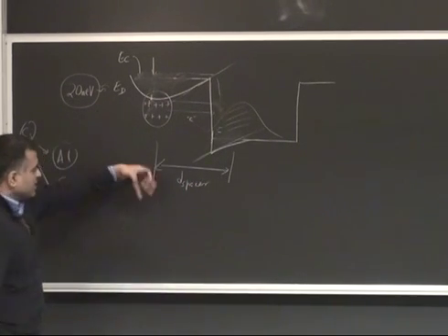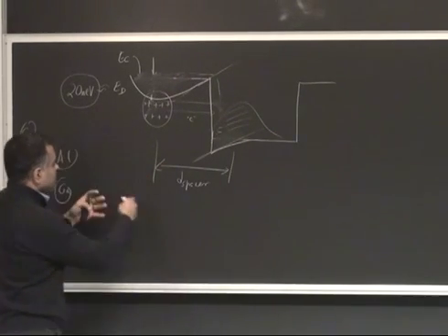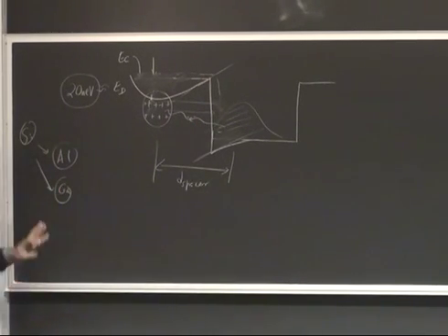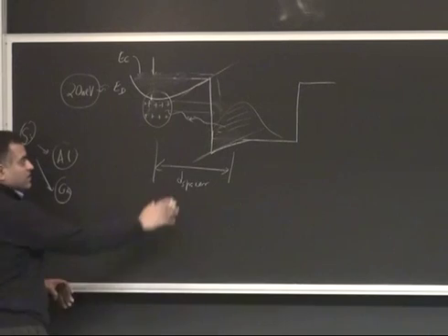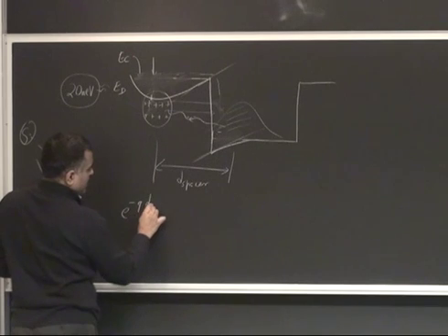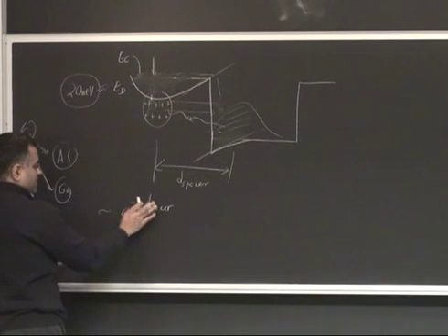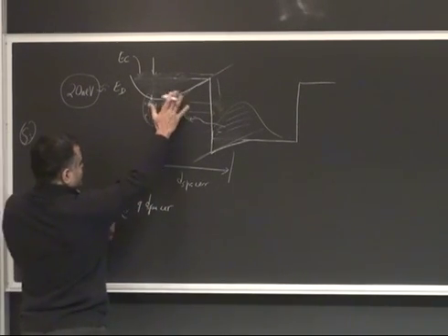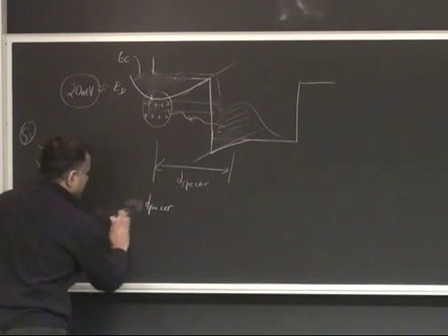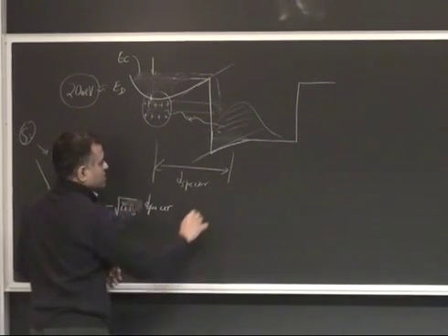And what happens is when you do the numbers, for example, if you look at transport properties for electrons moving in this direction, the mobility gets exponentially, meaning the scattering because of these ionized donors is exponentially damped based on how far you are from the electrons. So essentially, the mobility kind of goes up by a factor of this exponential, meaning the scattering rate is damped by this factor. And here, let me just write that down. I'm not deriving it for you, but it looks something like this: 2 pi times the carrier density, or the sheet density of electrons